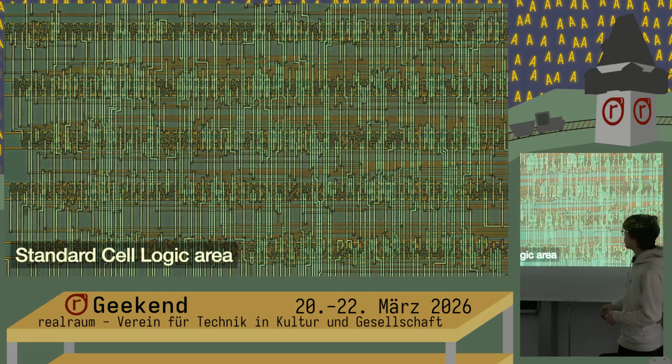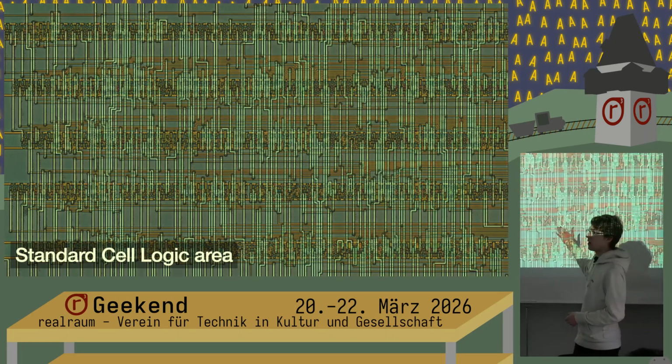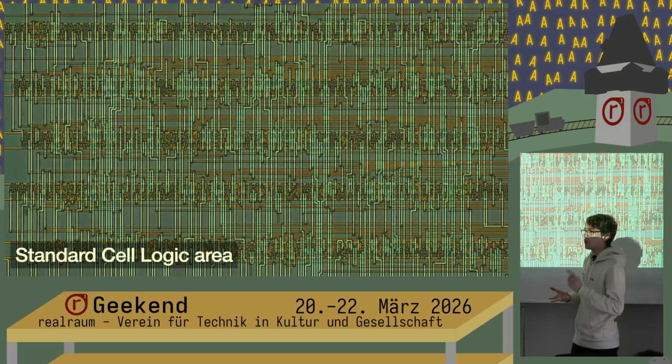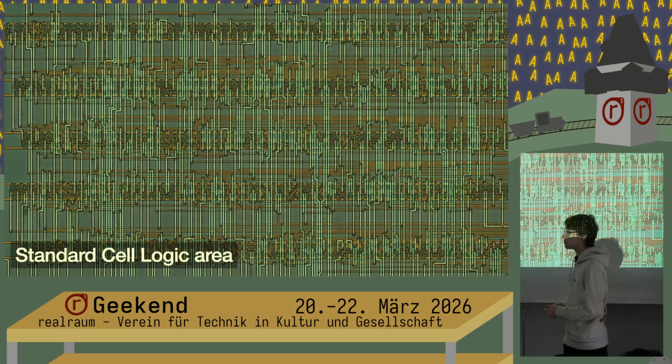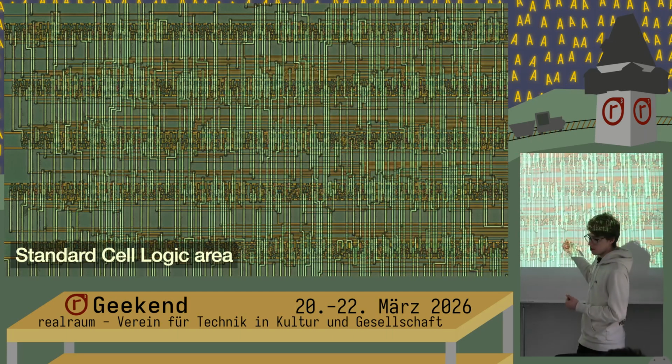Standard cell logic is something like this: essentially a bunch of AND or XOR logic gates, flip-flops, latches, and a lot of normal digital electronics, put together in a layout and all connected to form a very complicated circuit. That's essentially a way to convert code like Verilog into silicon, and that's how they manufacture the chip.